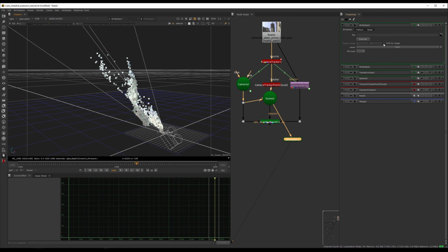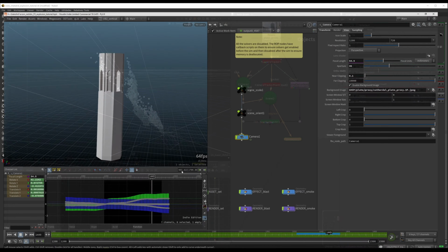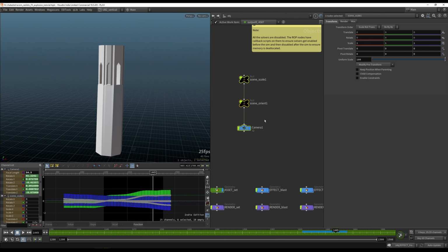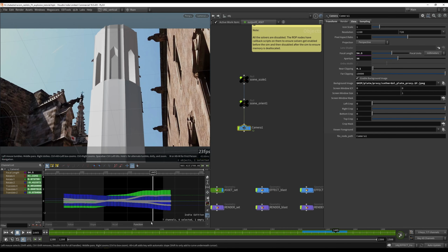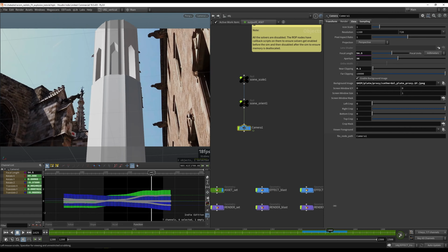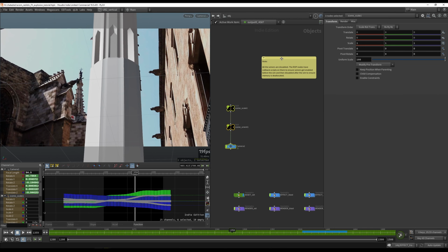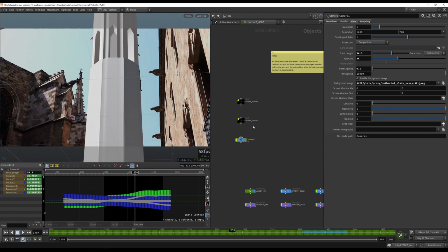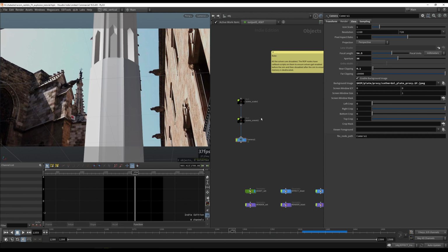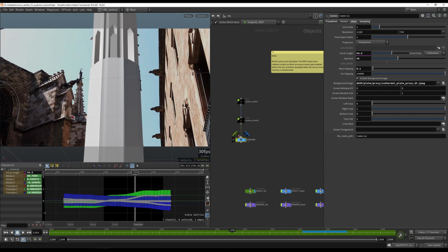So you can either export this as an FBX or ABC. In this case, this was using the FBX and I only imported the camera, and it works completely perfectly fine, as you can see. You can also do ABC, which is alembic, and it's going to bring in the camera plus the point cloud. I like it with FBX because you just get the camera. And by the way, these things, once you get the camera in, I'll show you. So let's do FBX or alembic.